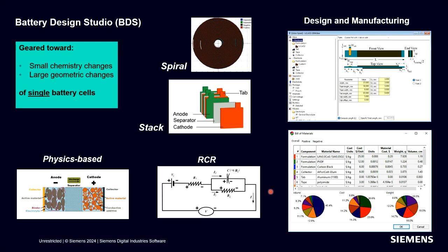Within Battery Design Studio, we include a physics-based model, so essentially plugging in the material properties and kinetics for the battery cell materials that you're using, and actually modeling the transfer of the lithium ion during discharge from anode to cathode, or vice versa during charge. And you get an idea of all the resistances of all these different components of the battery cell.